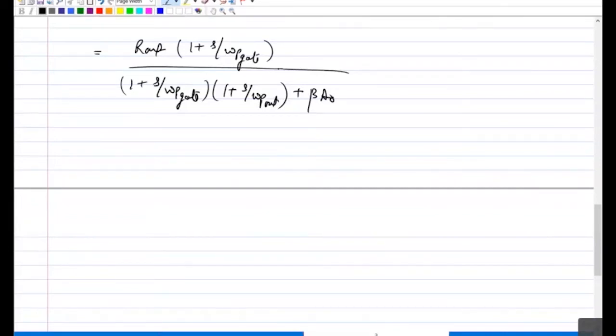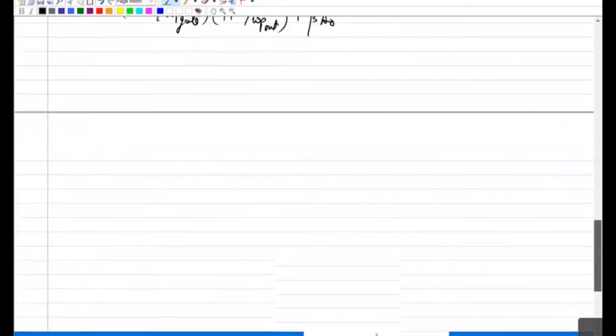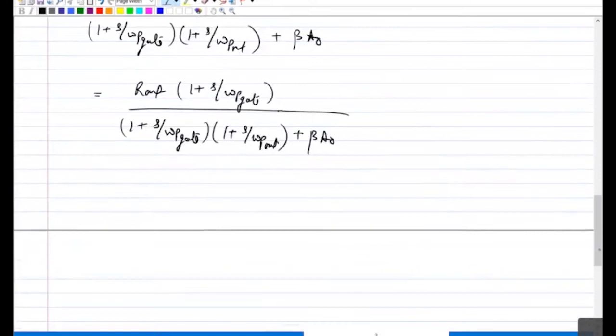Yeah, second order could be anything. Second order is not always complex. Okay, so it's a second order system. You have 1 zero and 2 poles. So if I'm only interested in doing the Bode plot, after compensation, what is the separation between the 2 poles, omega P gate and omega P out?